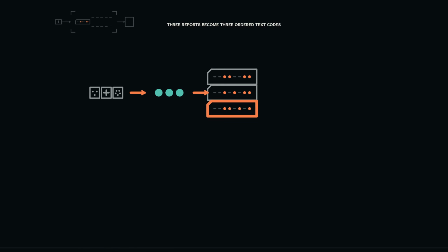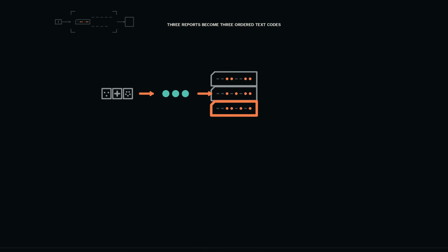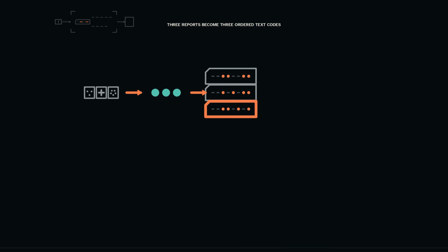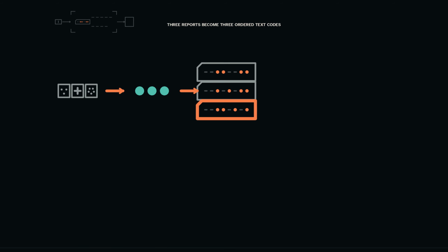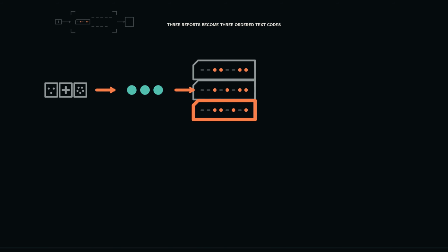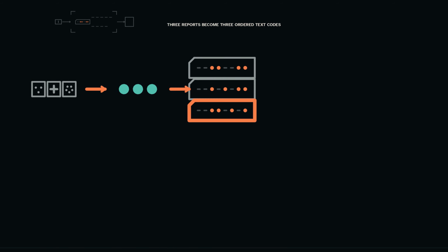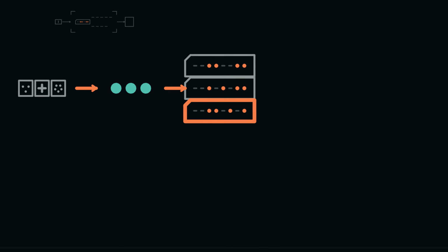The 3 bytes arrive at cycles 25, 95, and 175. Each arrival changes status for its own queue entry. The next status load sees 1, the branch falls through, and 1 data load consumes exactly 1 byte. The processor never detects a key shape or a complete equation. It observes ordered device state through addresses F0 and F1.